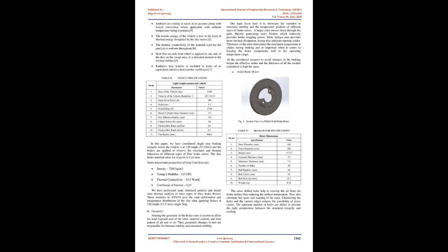According to different vehicle applications, vehicle manufacturers have variations of rib configuration in the disc brake rotors. They currently use 70 different rib configurations in disc brake rotors. These are straight, vaned or segmented. The reason to use so many kinds of rib configurations is to improve and maximize cooling and make them less noisy and reduce brake squeal. Different design and variations in rib configuration can change the airflow and noise characteristics in the rotor.